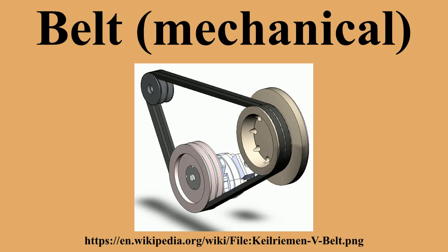To keep the driving part at its smallest, minimum diameter pulleys are desired. Minimum pulley diameters are limited by the elongation of the belt's outer fibers as the belt wraps around the pulleys. Small pulleys increase this elongation, greatly reducing belt life. Minimum pulley diameters are often listed with each cross-section and speed, or listed separately by belt cross-section. After the cheapest diameters and belt section are chosen, the belt length is computed.